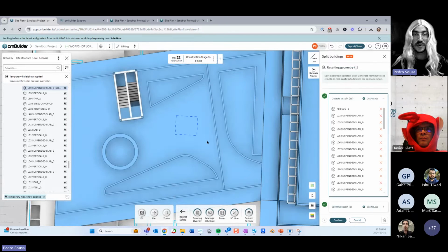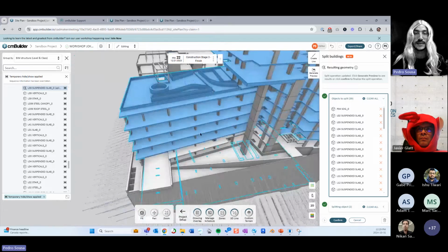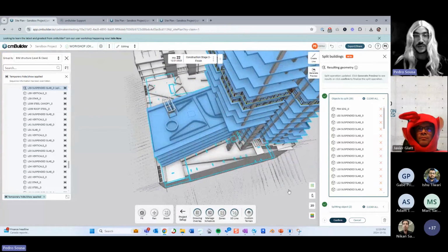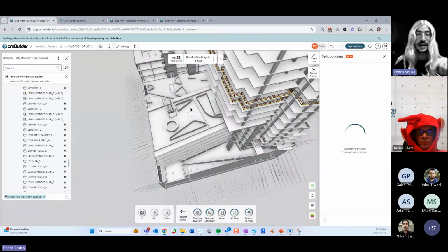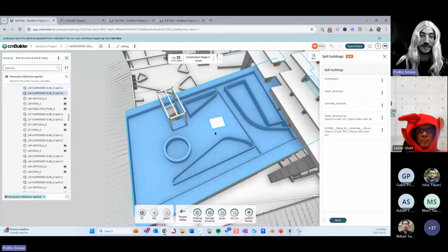And when I hit confirm, you see that that shape is self-contained. So again, we're going to extend this up and down to create a plane, a splitting geometry for those planes. And now that my slabs are already selected over here, I don't need to select them again. When I hit confirm, now I'm going to get this element in the middle separated from the rest.